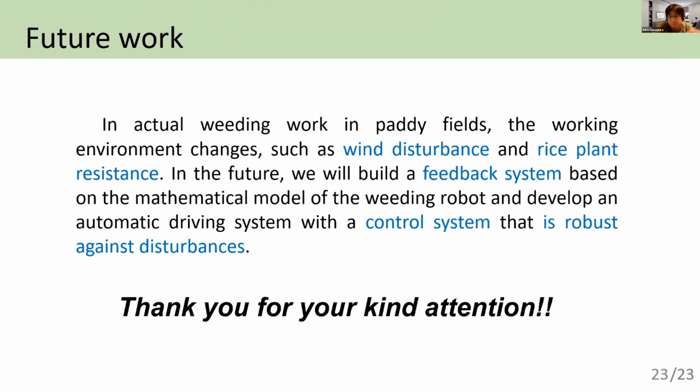Okay, this method is considered to be less likely to damage the rice because it floats on the water, except for the chain. We believe that this weeding mechanism is a method that can weed without damaging the rice. However, if the rice grows, the propeller may hit it. So I would like to take measures such as attaching a cover to prevent the propeller from hitting the rice.